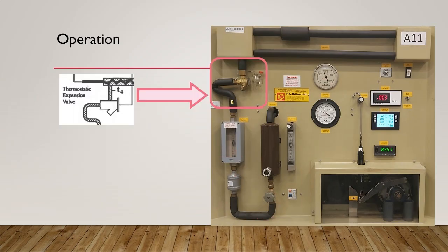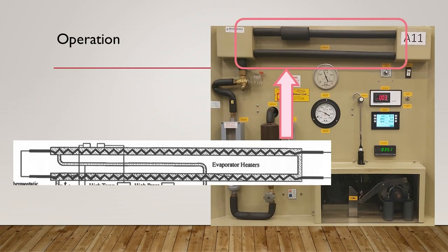Then the refrigerant passes through the expansion valve, its pressure would be lowered. At this moment, the temperature of refrigerant is very low. An electrical heat load is equipped at the evaporator. Students can adjust the loading along the experiment. So, at this stage, refrigerant with low heat energy would absorb and carry away the heat energy generated from the heat load. Then the refrigerant is transferred back to the compressor. This is the refrigeration cycle in this equipment.